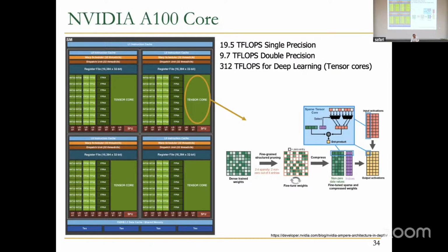You do a little bit more computation to figure out what actually needs to be computed based on the index of the element. So you say the element at row 0, column 0 is not a 0, so operate on it. The element at row 5, column 200 is not a 0, operate on it. That's what this index means, as opposed to storing zeros. It's a different format, and this tensor core can now operate on this format so that it gets rid of unnecessary multiplications by zeros.